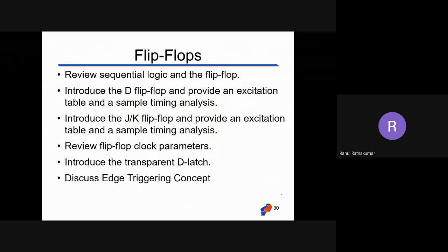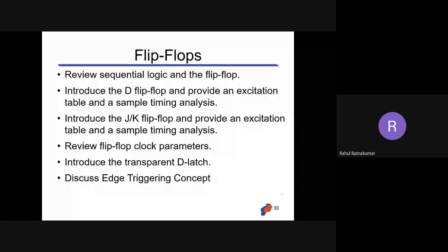Now, flip-flops. Difference between flip-flops and latches. Flip-flops are edge triggered. We have positive edge and negative edge of the clock, and flip-flops are designed such that there are fewer issues of level triggering, like multiple switching. You can have multiple switching within one clock, so we can't control the outputs, how many times the output is going to switch, in level triggering or latches. Flip-flops are limited because they switch on the high going edge or the low going edge.